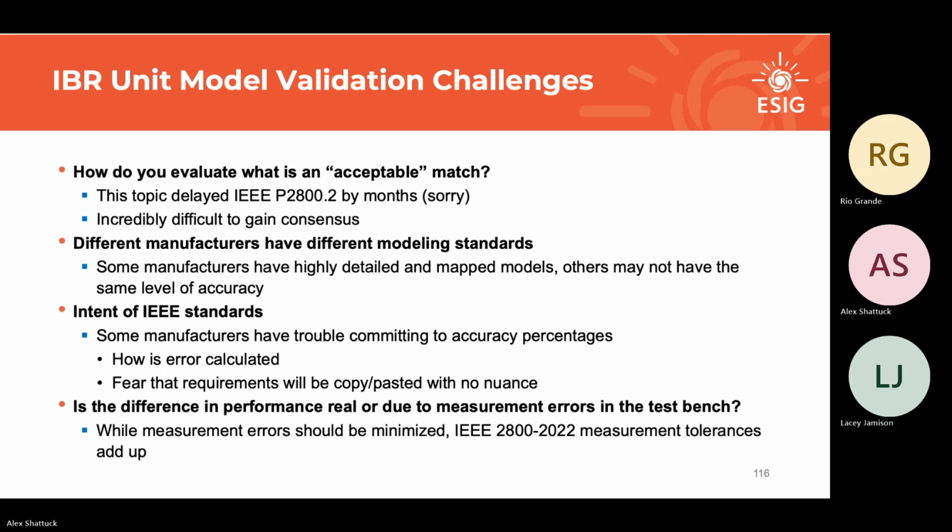The other piece, somewhat related to the first one, is the manufacturers have really different modeling standards. We talked about, I guess, yesterday morning, user-defined models were very bad 10 years ago. Some manufacturers who were prominent in the markets that were really heightening their requirements may have made decisions that will help in the future, right? So some may have gone to full code integration or really detailed block diagrams or parameter mapping. Others didn't, which means there are certain situations, especially in the extreme fault tests, where they may have a pretty good model otherwise, but they're at an error that's just outside of what we agreed to.